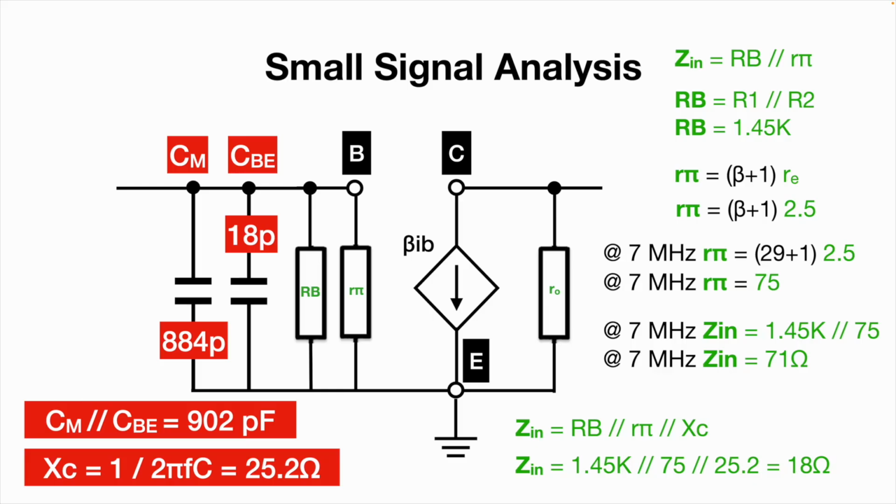There may also be other stray parasitic capacitance knocking around that I've not even bargained for in my own calculations. So there's going to be a bit of difference, but don't let that trouble you too much. Really, what I want you to see is the overall effect. But I think it's undeniable that this capacitive loading of the input impedance by the Miller effect is a big deal and makes a big difference.